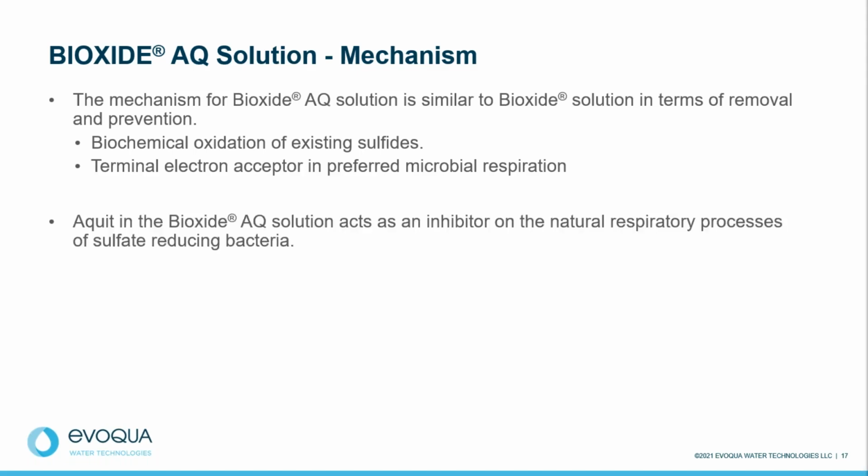The anthraquinone, also called AQ, that's present in the BIOXIDE AQ solutions, acts as a natural inhibitor to the respiratory process of these sulfate-reducing bacteria, which results in lesser production of sulfides and, in turn, hydrogen sulfide gas.